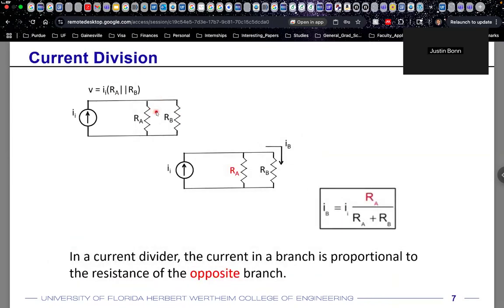All right. So in terms of voltage distribution and current distribution, we have looked into both. You know that when we are looking at series resistances, a voltage develops across each of those resistances. Let's say you want to know the voltage developed across the resistance RA. Then that voltage will be proportional to the value of the resistance RA. On the other hand, if you want to find out the voltage developed across RB, that will be proportional to the value RB.